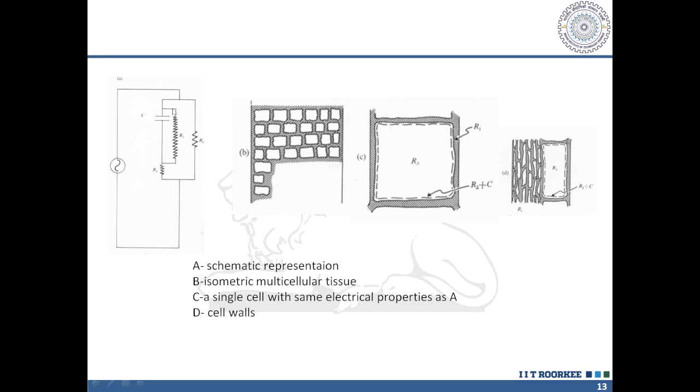Here you can see in this diagram we have a parallel RC circuit, which is connected with R3, and then they are connected in parallel with R1. So from this circuit we can conclude that conductivity changes with the change in frequency, because the capacitor impedance changes with the frequency. So why are we getting different images?